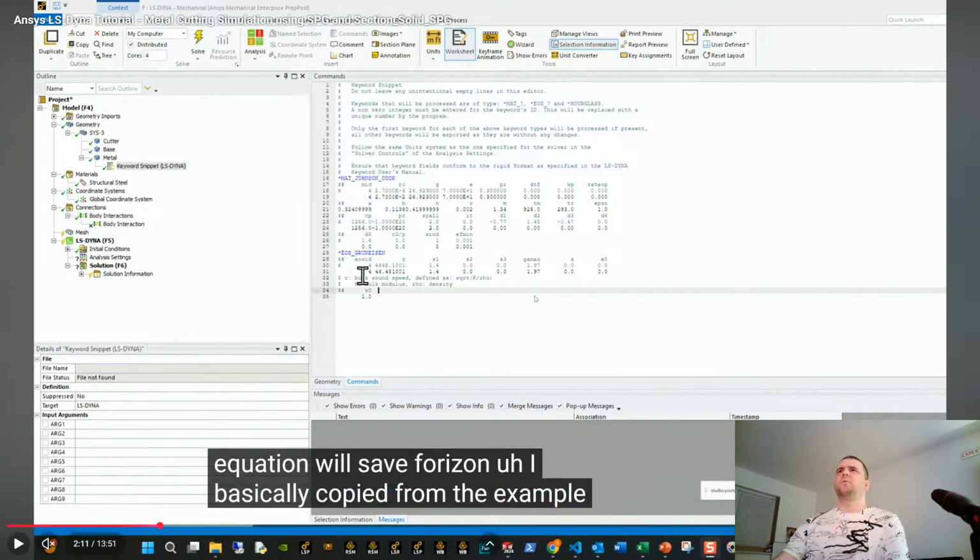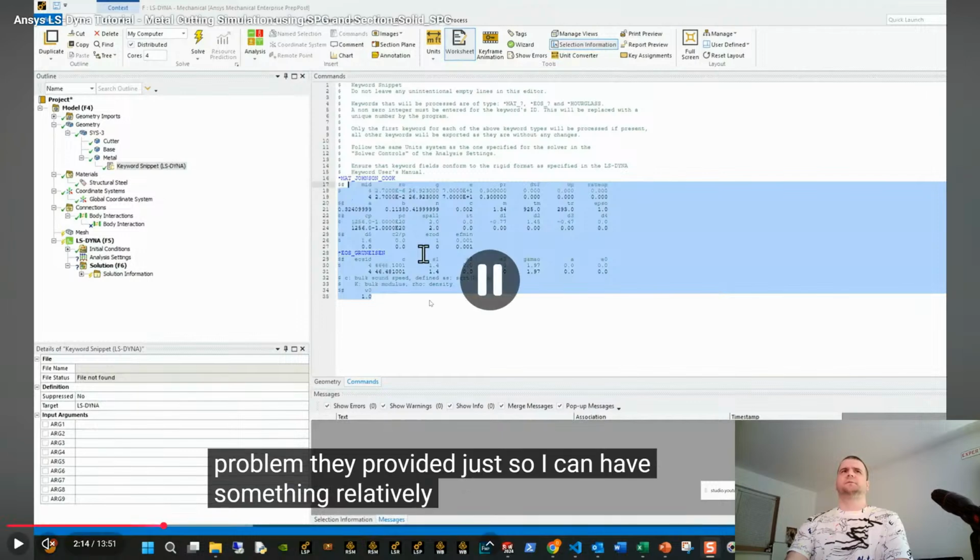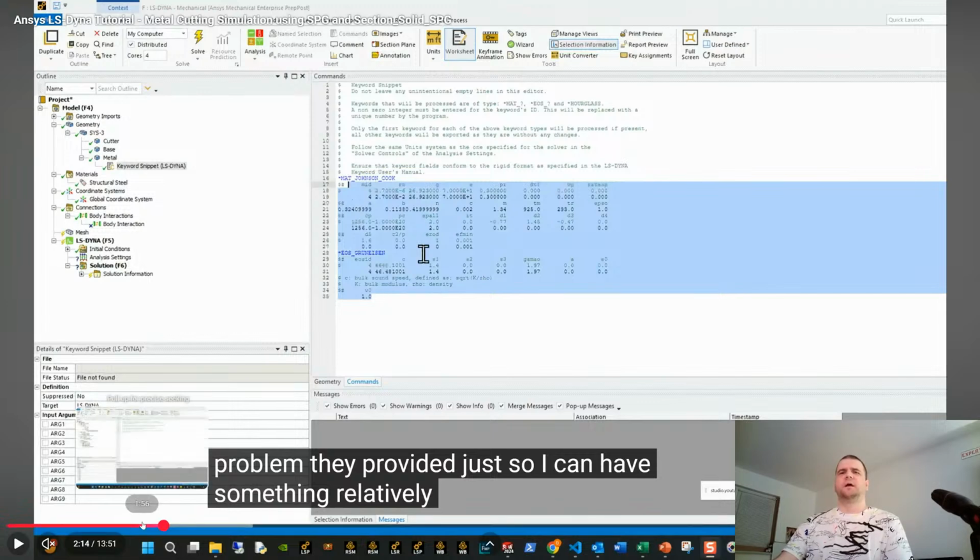Now let's see what ANSYS version he has. He doesn't show the ANSYS version, because in recent ANSYS versions we can also select LS-Dyna materials. So he uses a default structural steel, then inserts a command to convert it to aluminum defined as in LS-Dyna.